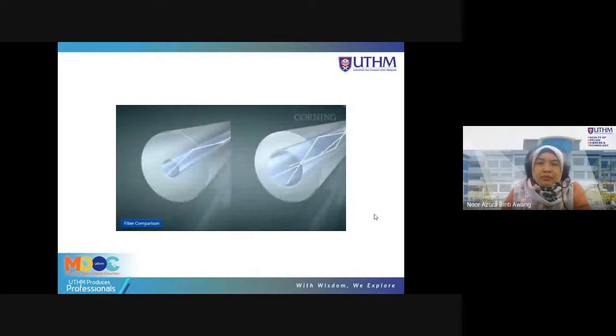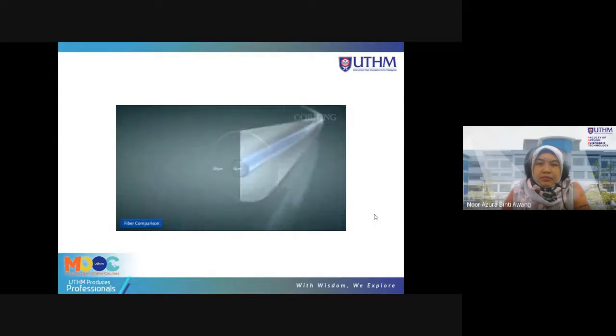There are two different types of fiber, single-mode and multi-mode. Single-mode fiber has a small core diameter designed to carry light in a single path over long distances. It has high information-carrying capacity and low attenuation, and is the most widely deployed optical fiber in the world. Multi-mode fiber has a larger core, which allows light to travel down many paths simultaneously. Typically, multi-mode fiber is deployed in data centers, local area networks, and storage area networks, where it is more cost-effective than single-mode fiber.